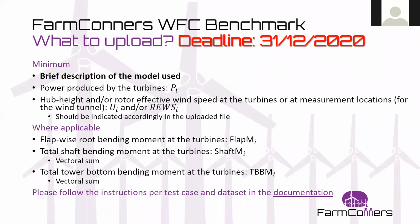Wherever applicable, depending on the fidelity of your model, we also expect you to upload flapwise root bending moment at the turbines, vectorial sum of the shaft bending moment at the turbines, and vectorial sum of the tower bottom bending moment at the turbines. There are very clear instructions listed in the documentation, so please follow those instructions before you upload your results.